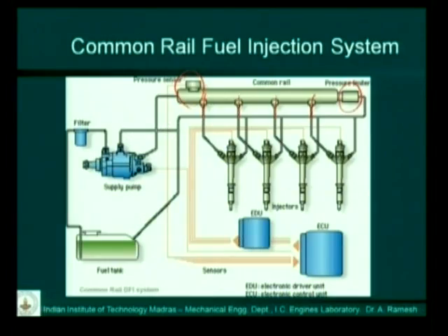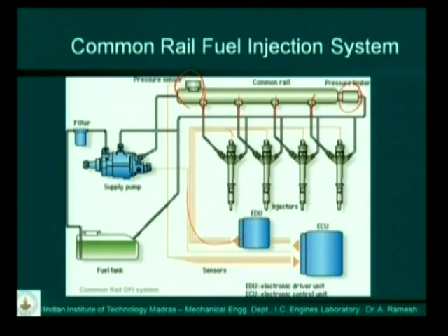And this high pressure fuel is allowed into each one of these injectors. The high pressure fuel is supplied to these 4 injectors, and the ECU controls the 4 injectors through these lines. Whenever it wants to inject, it sends a pulse to that injector, and now it sends 3 or 4 pulses to every injector in every cycle, and sequences and operates this. The excess fuel from the injector comes back to the tank. The excess fuel from the pressure rail also comes back to the tank. So this is how the system works.